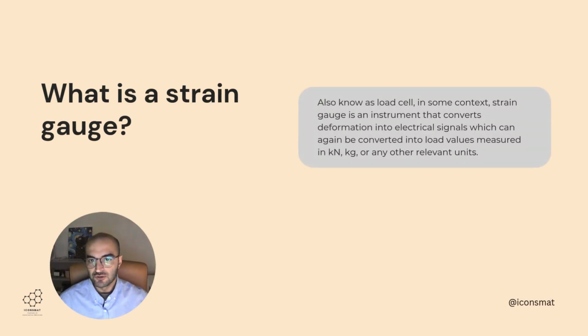Firstly, as to the answer to what is a strain gauge, also known as a load cell in some contexts, a strain gauge is an instrument that converts deformation into electrical signals which can again be converted into load values measured in kilonewton, kilogram, or any other relevant units.